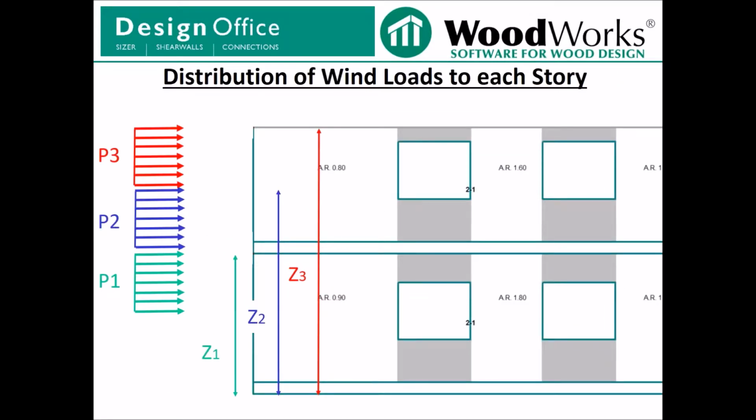In this slide, we will discuss how the wind pressures generated in the log file are distributed to each story as line loads. In the next slide, we will go over how line loads are distributed to each shear line within a story. In this case, we're looking at a two-story structure with a flat roof. On the first story, there is no wind load generated on the bottom half of the wall, and it is assumed that all wind loads on the bottom half of the wall in the first story go directly into the ground. For each story, the wind pressures are split in half.